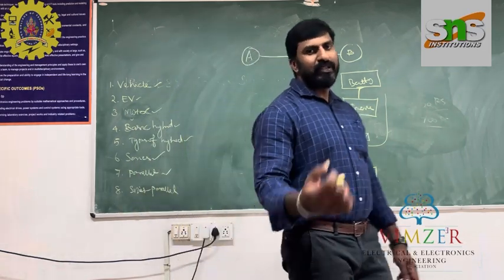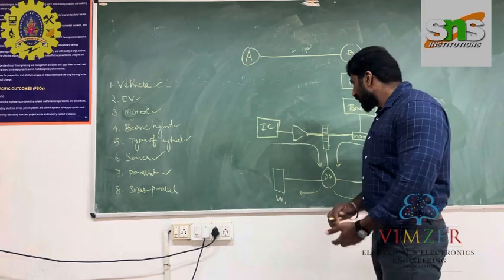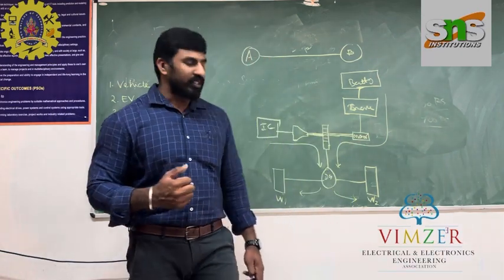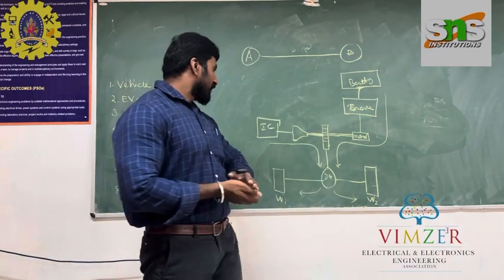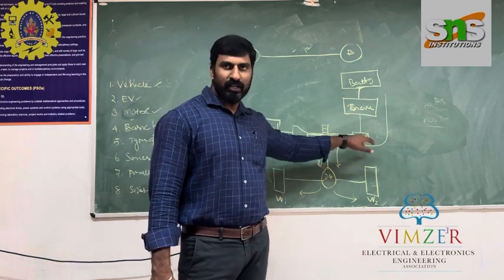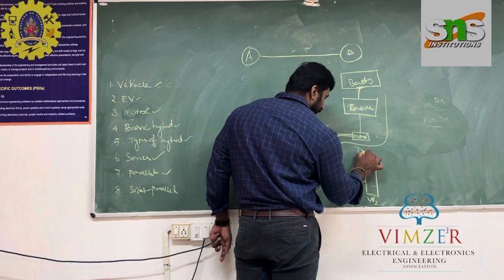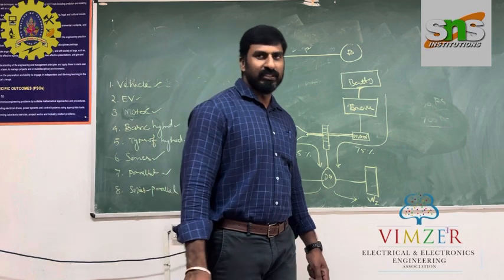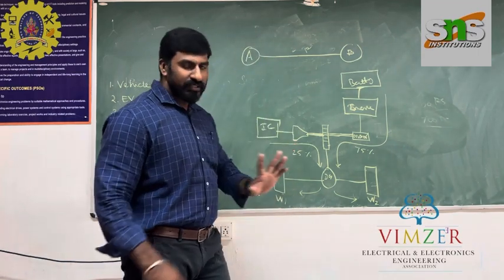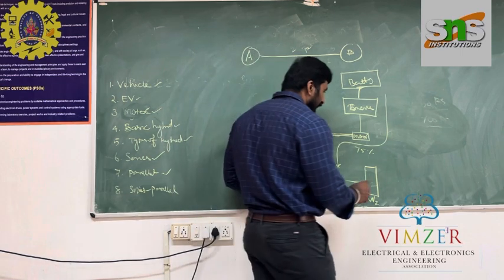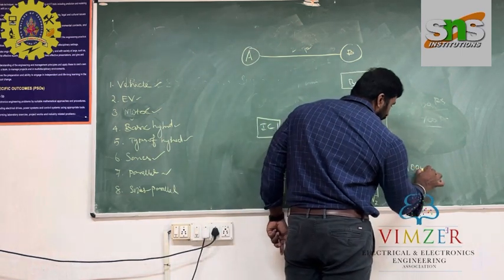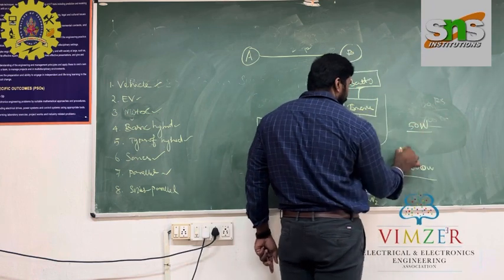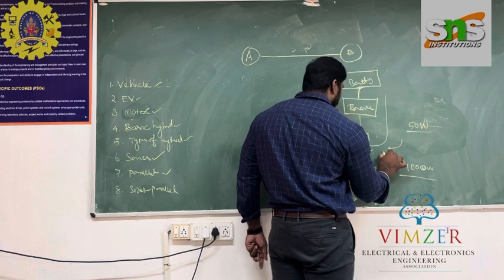Okay. So what are the pros and cons? The pro is that the vehicle can experience a high power rating of torque. For example, when the vehicle needs a large amount of power, this power is supplied by the motor. For example, the motor will give 75% of the power and the remaining 25% is given by the internal combustion engine. Just assume the vehicle needs 1000 watts of power, but the battery has 500 watts. The remaining 500 watts is taken from the IC engine.